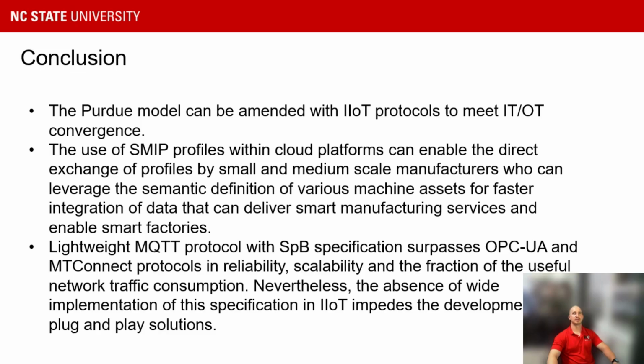Existing IT systems do not have functionality of direct access to the MQTT protocol. Thus, they have to retrieve the data from a database, which violates the idea of a unified namespace. Future work in this direction is needed to ensure that IT software vendors have the ability to communicate, subscribing directly with the MQTT broker. Sparkplug B was only released in 2019, and further revisions are available now. We expect that adoption by the industry can lead to a better implementation of this protocol.